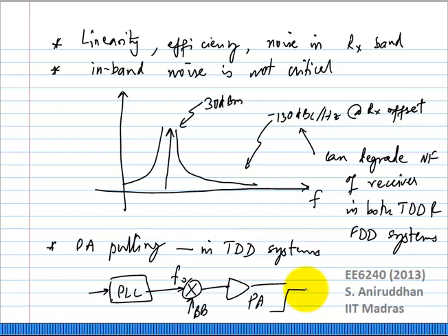Now when you turn on the power amplifier, because of the PA turn on transient, it is suddenly pulling in a lot of power from the supply. Maybe you get a very big jerk on the supply. Similarly, the PA may use an inductor which may be magnetically coupled to the inductor in my VCO. Okay? So what happens is, normally when you try to do something like this, the VCO frequency will go off momentarily and then come back on.